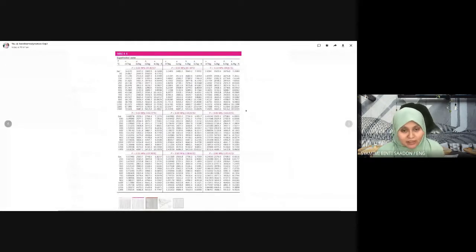Because we know the whole of this table is in vapor form. The substance water is in vapor, and it is heated. The water in the piston is heated, so obviously it will become more and more vapor, not liquid. So we just take the nearest possible value to 2865. We have this one, and we look at the temperature. Temperature is 200 degrees Celsius. So that is the final temperature, T2 or T final. Okay?